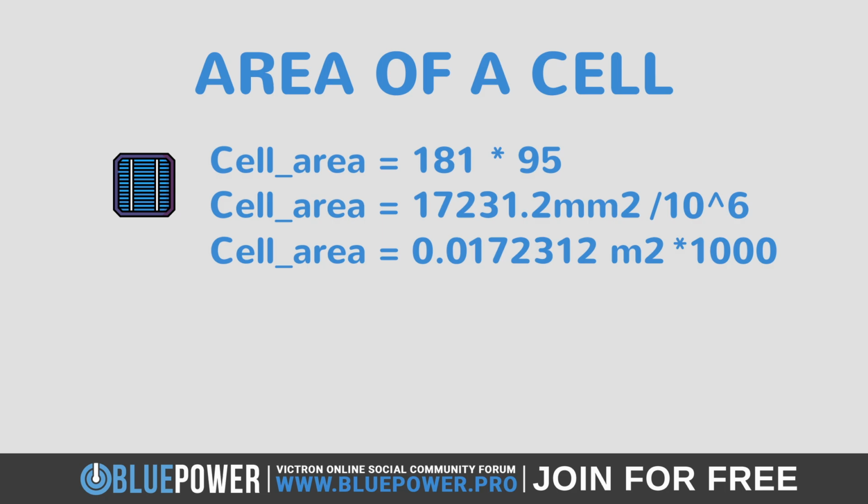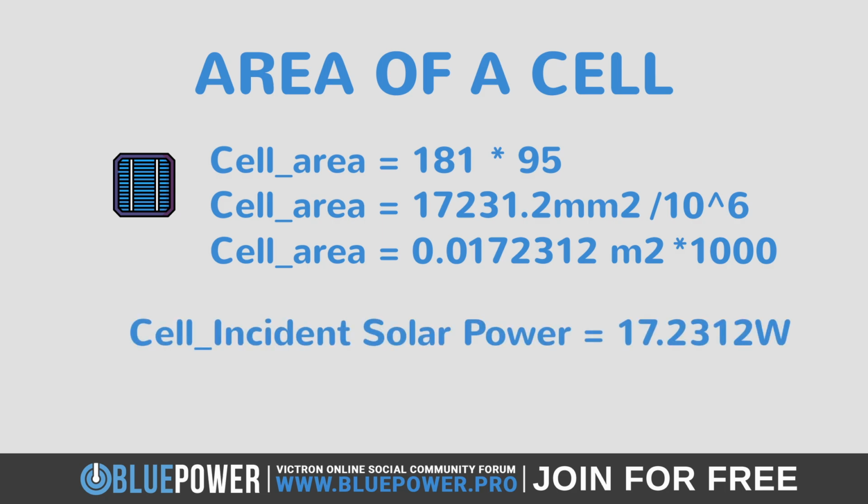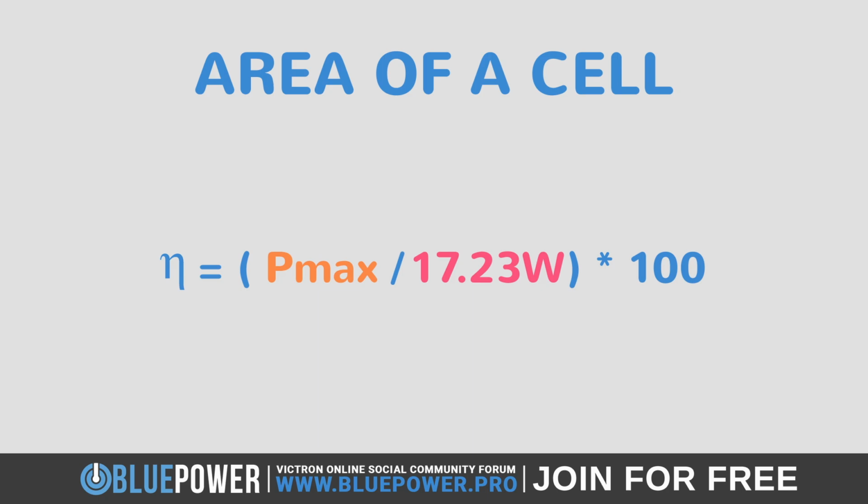Next, we multiply this by 1,000 irradiance, giving us the incident solar power of 17.23 watts. Great, let's finish this off by plugging this into our efficiency formula as the denominator. However, we have one more step to factor in. We cannot use the original 425 watt Pmax as the numerator, as this is for the total module's power output.